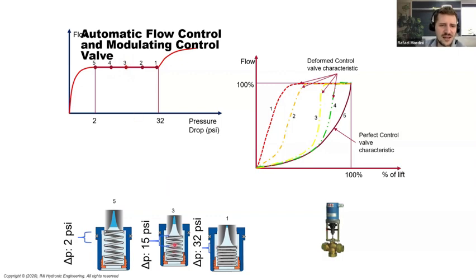It means that this spring here is halfway down compressed, and now the area of passage of the water decreased, the CV of the valve changed, so the flow rate stays the same, right? But look at this. This is going to be the control curve for the control valve here. Imagine that we want just 10% less heating on that room. So you send 9 volts, right? 9 volts would be 90%, something like that. As you send 9 volts, the control valve closes a little bit.